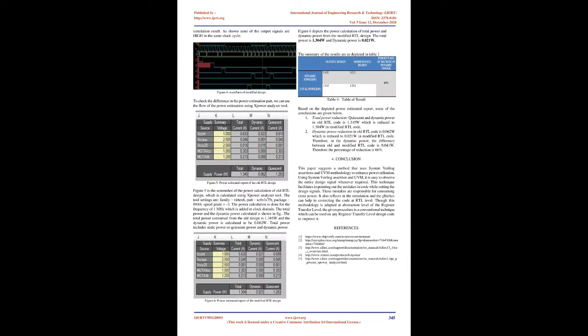On the contrary, a clock signal is absent in a combinational circuit, which does not allow a SystemVerilog assertion to identify glitches. For this type of RTL design, it is convenient to choose an assertion which can catch the functional bug in the clock signal. The chosen RTL design with the functional bug is shown in figure 3. The functional bug that is affecting the power consumption of the whole design can be found by writing a SystemVerilog assertion in the UVM environment test bench.